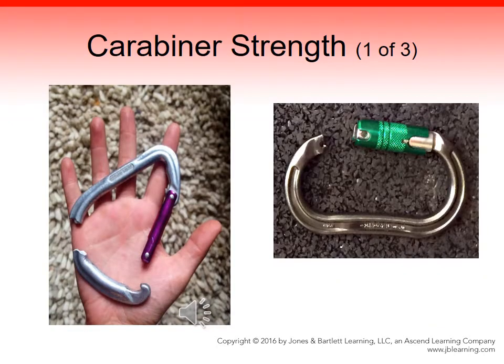As with everything we use today, some carabiners are not as strong as advertised, especially when the locking knob is in the unlocked position. For these designs, the locking knob must hold the claw-type latch together in the lock position to have its full rated strength. Tests have shown that some designs can fail if the gate is unlocked. Carabiners are subject to fail when they are overloaded, whether the gate is closed and locked. Again, as technicians, it is your job to use the right tool at the right time.